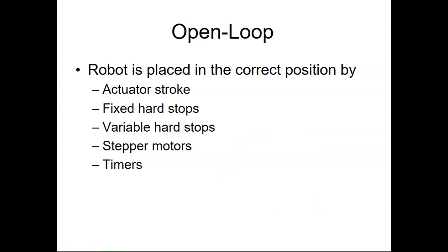And then we use timers on this as well because it has no real feedback. We set the limit of its movement usually by time and with hard stops. Because these are things that run on stepper motors. Stepper motors are like a clock again. It doesn't know what time it is. It just knows that it needs to keep the little hand moving, right?